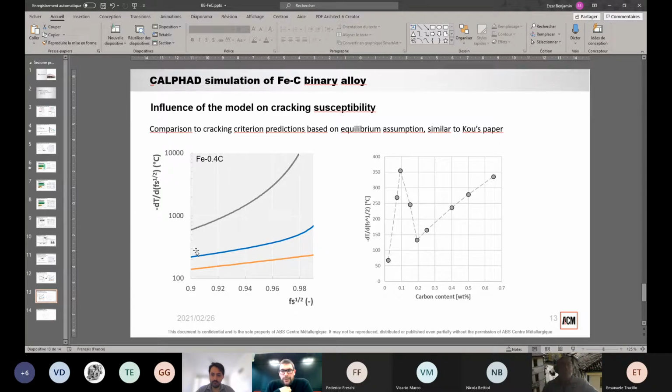And just to comment on what you said about casting conditions, what we often see is that medium carbon steels are not that easy to cast. In big sections, here we see that it seems not to be so difficult with them if we just look at the curve, and in reality it's not that simple.